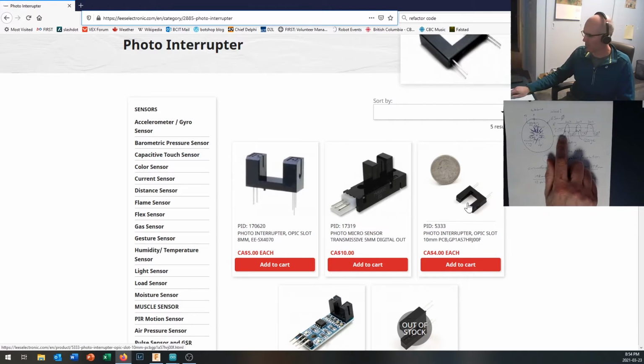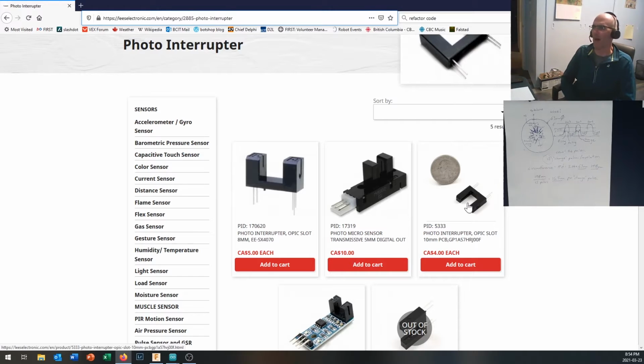You get crisper signals. You can see I've kind of rounded off the top and the bottom right here, and we'll take a look at why I've done that when we take a look at some readings with our DP scope. But if we were using a photo interrupter circuit and we were spinning a disk between them, it would be very precise and very sharp transitions. So technically, if you're designing something from scratch, the photo interrupter is a slightly better sensor than a reflective object sensor.